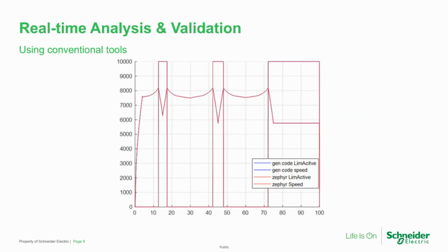And what there is here is that it's not two curves; it's like 2 times 2 curves, because they are completely overlapped. The application is giving the same output based on the same inputs. It means that even if the code is loaded via LLEXT, it does exactly the same thing at the same time. So in terms of real time and in terms of behavior, it's exactly the same. So there is no drawback with the LLEXT subsystem.